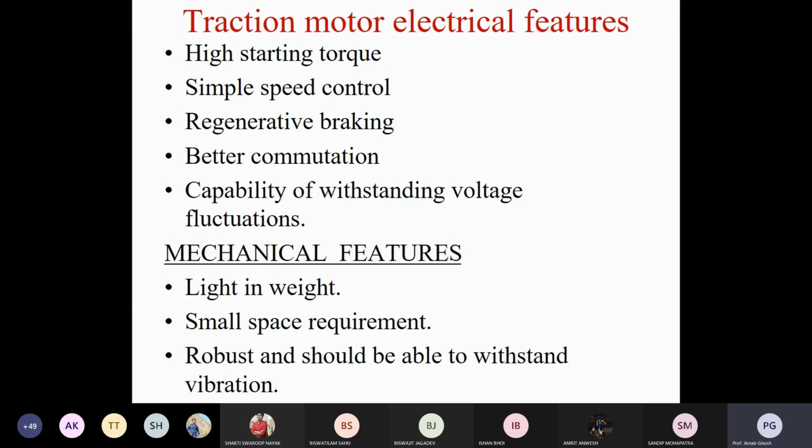Then the prime mover speed of the test motor becomes more than its normal speed. Since it is more, you can see it acts like a generator. On the zero-crossing ammeter, the current comes back to zero, and then the ammeter shows a negative current. By this way you can see the regeneration.